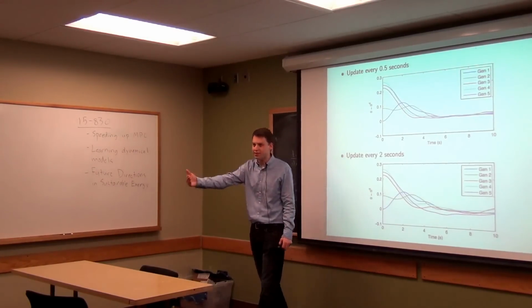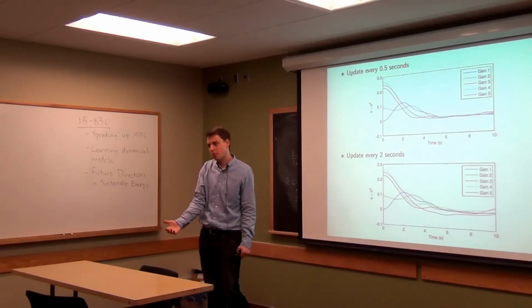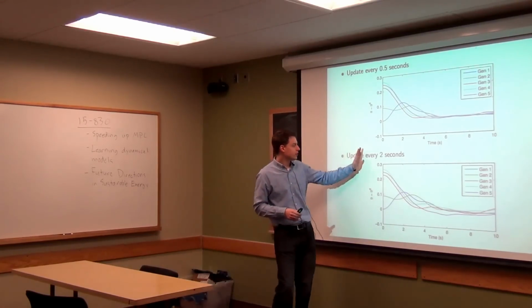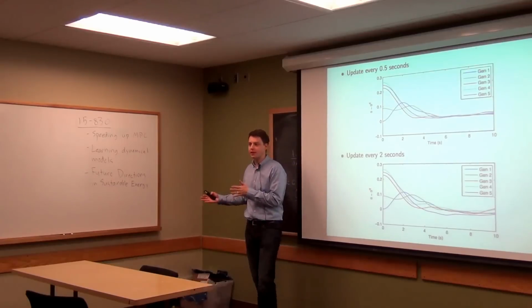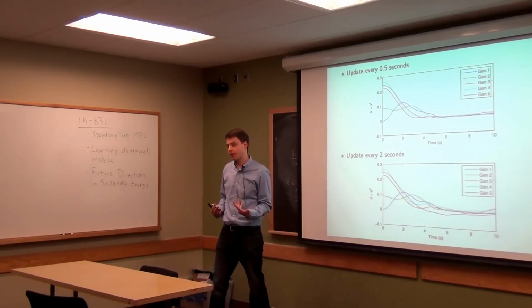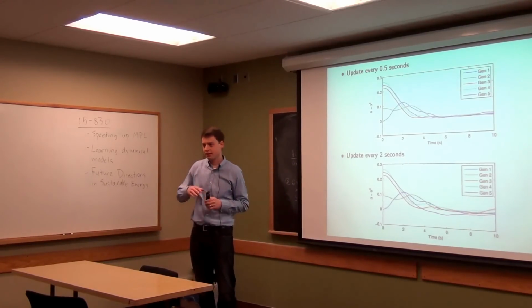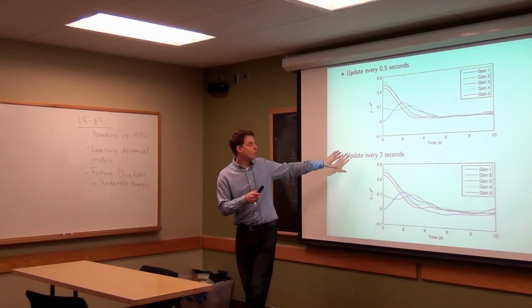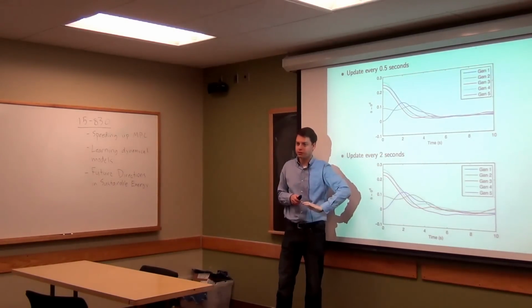So the right amount you can shorten that internal planning horizon for MPC, and the right amount you can go between updates, that's all very problem dependent. And it's going to take basically some trial and error, or maybe some understanding of the system that you actually care about, to know what settings you want to use for these different things.